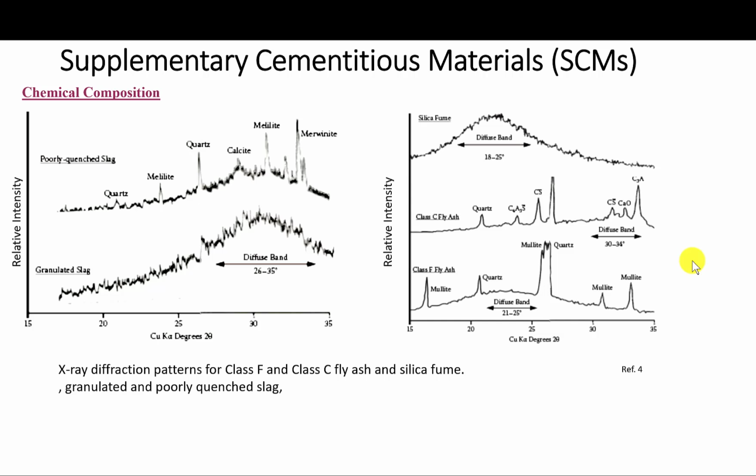Natural pozzolans basically have more variable glass content ranging from 50 to 90%. The principal crystalline compounds are quartz and feldspar, but when we have volcanic tuffs or ash, they may contain other materials called zeolites, which, although crystalline, have some pozzolanic behavior.